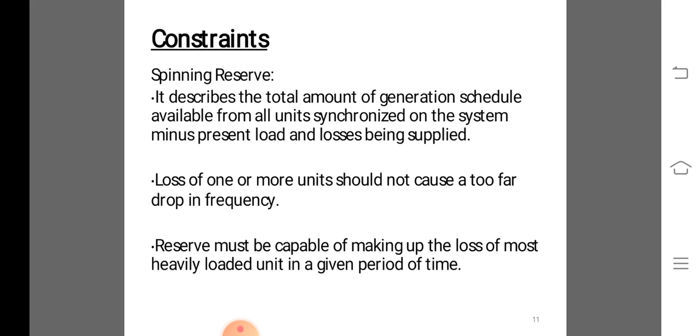Many constraints can be placed on the unit commitment problem. The list presented here is by no means exhaustive. Each individual power system, power pool, reliability council, and so forth may impose different rules on the scheduling of units, depending on the generation makeup, load curve characteristics, and such.